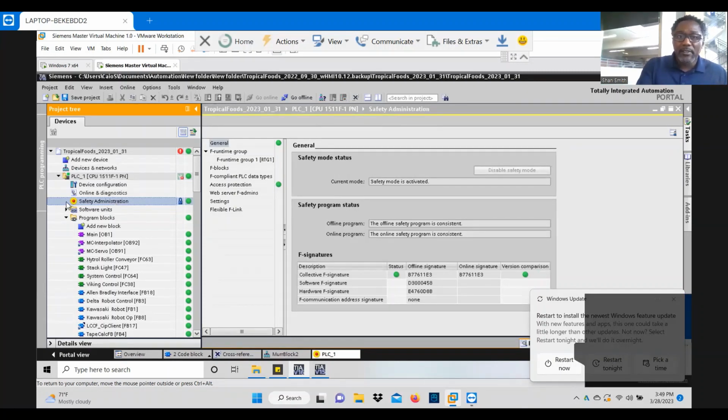Please have it. So let's talk about your safety program real quick. I'm not going to go into it, but one thing you do need is a safety signature. That safety signature protects the company. The safety signature protects the integrator, meaning that once I've completed all my functional safety tests, light curtains work, e-stops work, everything stops in your standard time for safety.